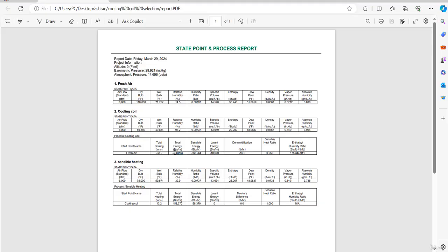So this is the total energy required for cooling coil. So the load of our cooling coil is 34 ton. If we want to get this temperature and relative humidity, we use a 33.9 ton cooling coil, and then for achieving our comfortable level of temperature, like dry bulb temperature 50 degree Fahrenheit, we should add sensible heating.